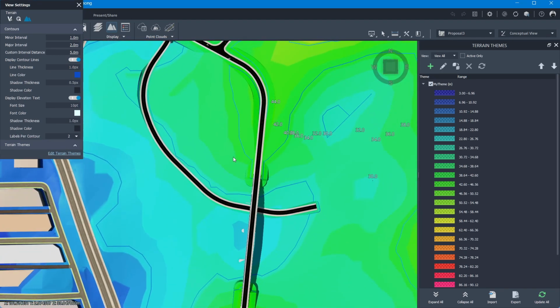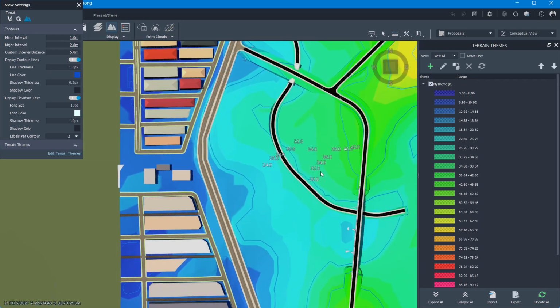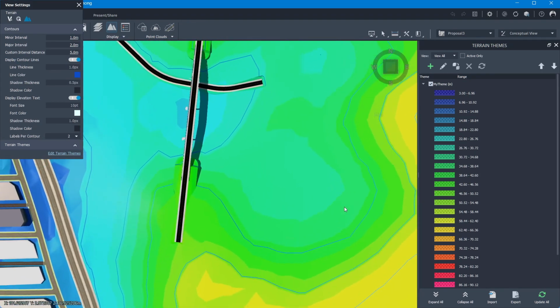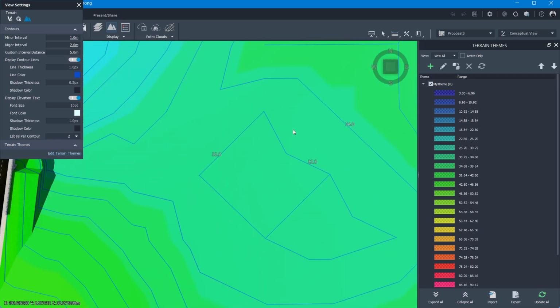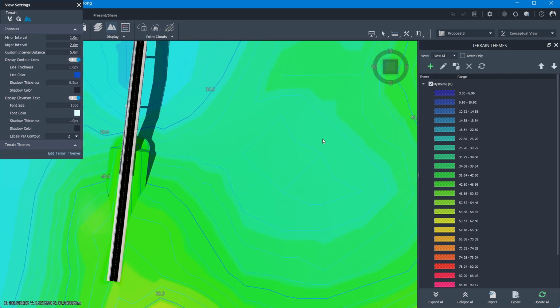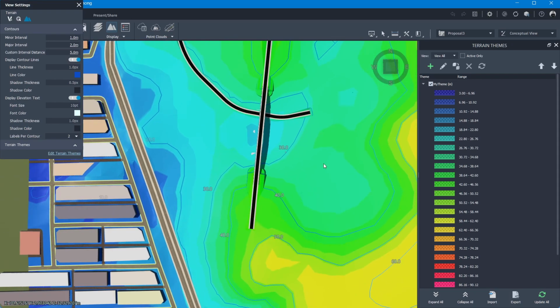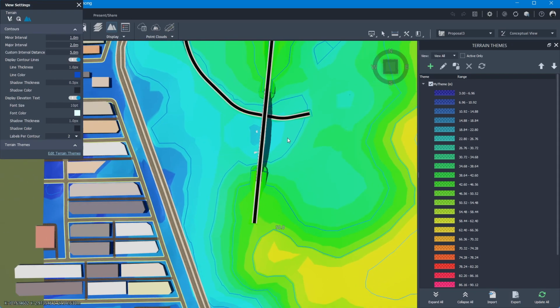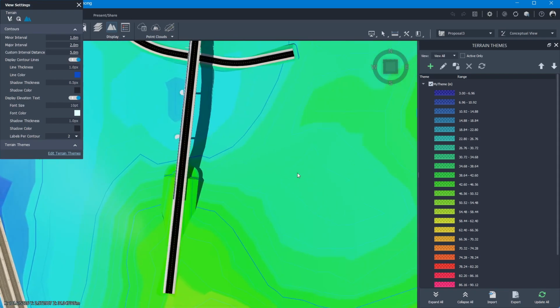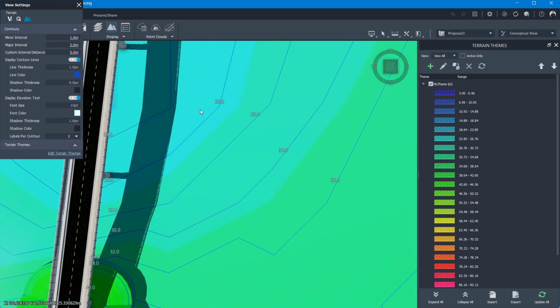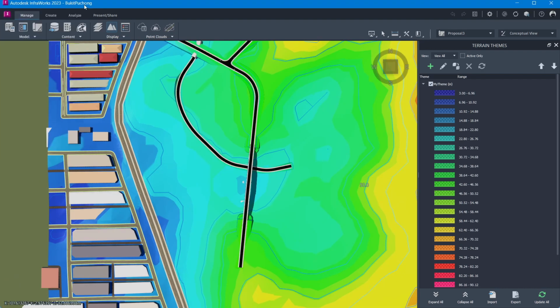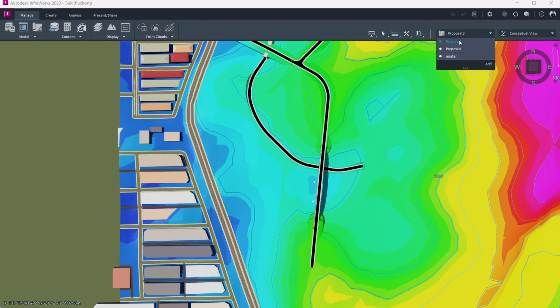See here, basically the area has different elevations, quite gentle. You can select this area, which has 2 meters of difference in elevation. So maybe this area is suitable for flattening, but this area is too low. Very low. The area is 30 something, 32. The lowest point here is 26. Then I already created the grading, close to proposal 4 here.